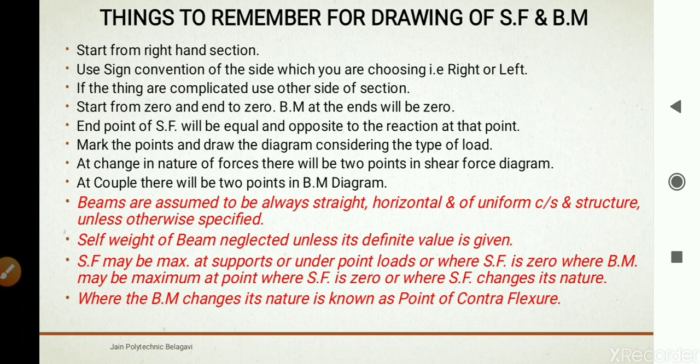Things to remember for drawing of shear force and bending moment diagrams. Okay, so these are some important points to remember. If you get confused when you draw, or if the concepts are not clear, these points are going to help you very nicely to draw the shear force diagram and bending moment diagram. Start from the right hand section, that is to the right of X, just what we discussed. Use the sign conventions of the side which you are choosing, that is right or left.